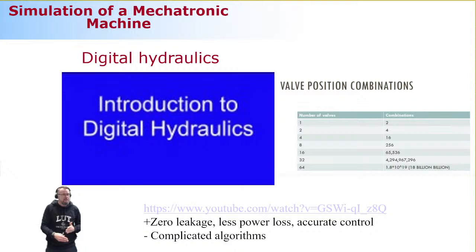the energy that you needed. This kind of combination seems to have a lot of promise, because now you can work in a way that the energy leaving the pump travels all the way to your actuators with a minimum amount of pressure losses. Why is this great? Because the pressure losses are also the energy losses. So then you have the highest possible energy efficiency, or let's say you can enhance your energy efficiency by using this kind of digital hydraulics.